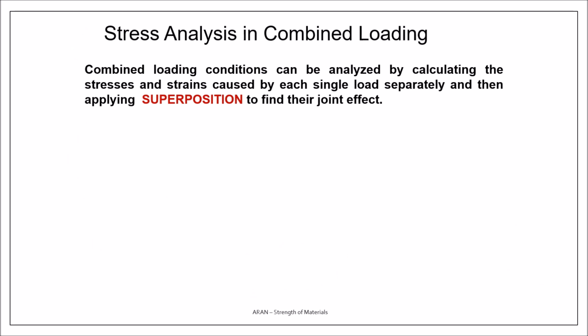In combined loading, we have to calculate the stresses and strains caused by each single load separately, and then apply superposition for their joint effect. So it's not too complicated: we consider each loading separately, calculate the stress distribution, and then sum their effects by superposition.